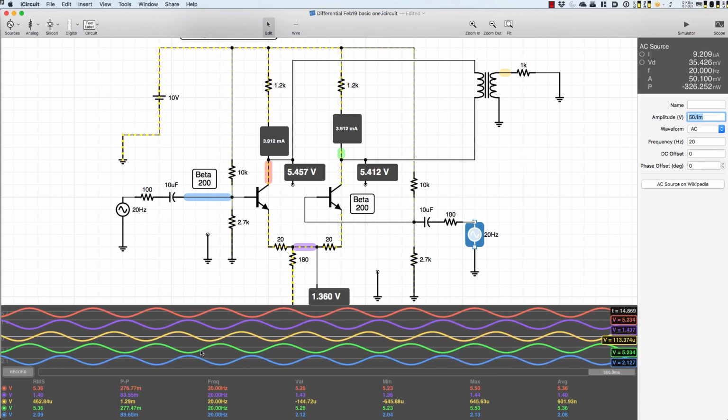I'll pause it. Now I've got an output situation on the yellow because now I have a difference between the Q1 collector and the Q2 collector. Only a tiny difference, only, what's that, 0.1 of a millivolt. That's 100 microvolts of difference that I've got between the 2 signals. It's more than enough to upset the balance in this differential amplifier now and give me an output situation between the 2 collectors.